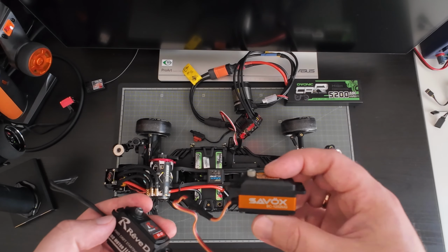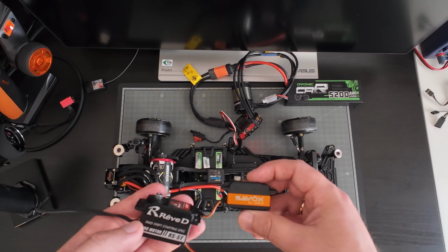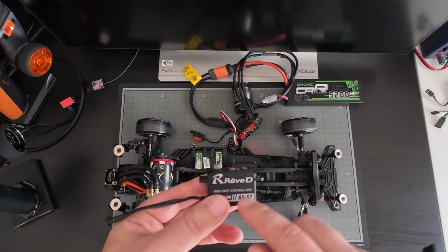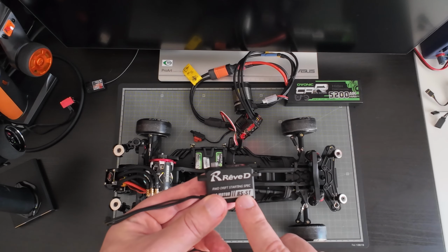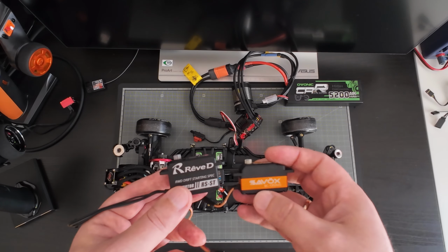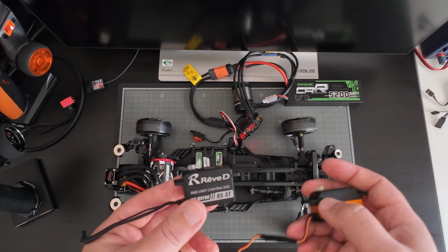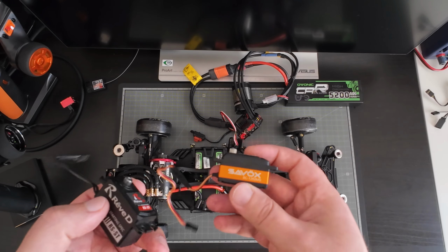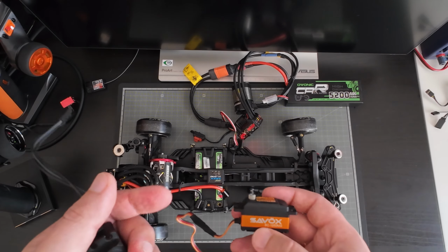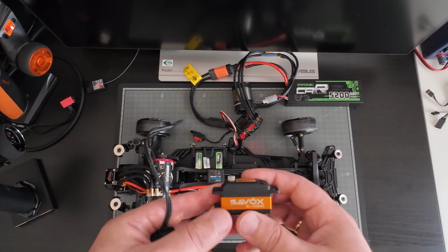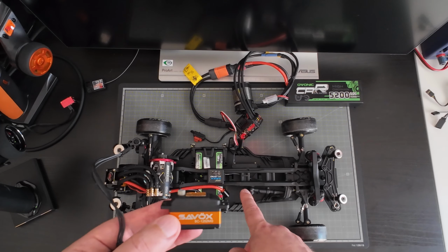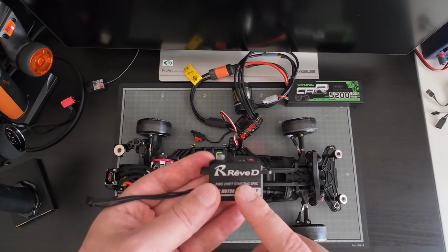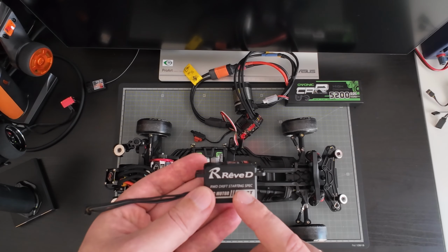This has a coreless motor inside the servo, where the Rev D RSST has a newer Pro version, which also has this coreless system inside for the motor. What coreless helps with is speed. So this small Servos servo has almost twice as much speed as this specific servo here, and that includes this Rev D. This Rev D actually is quite a slow servo.